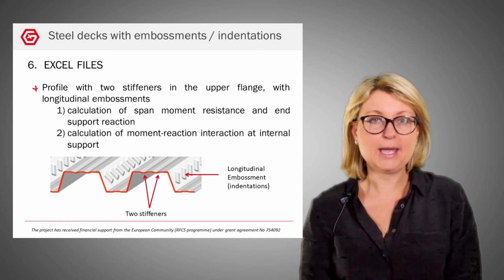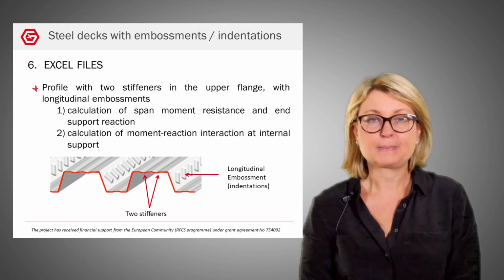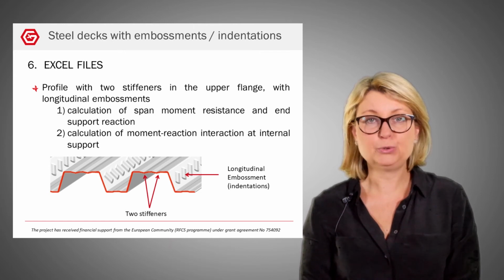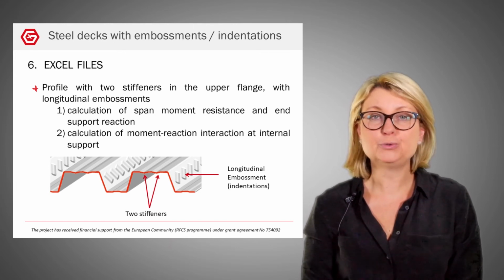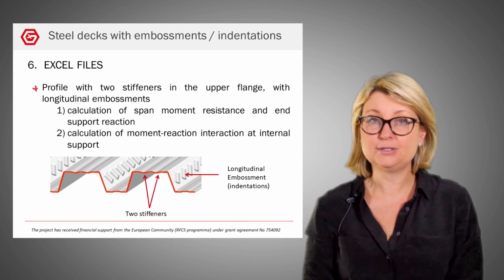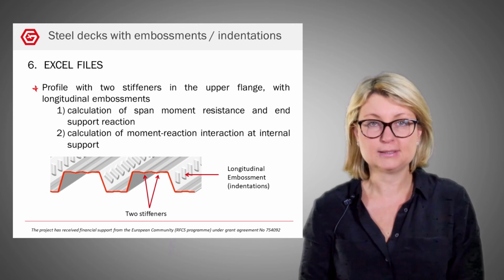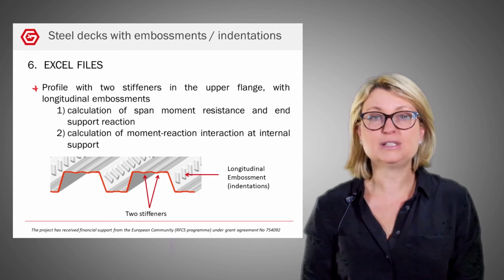You will also be able to calculate span moment resistance, end support reaction and moment reaction interaction at internal support for a profile with indentations and with two stiffeners in the upper flange.